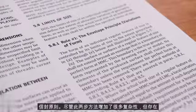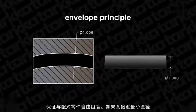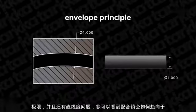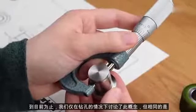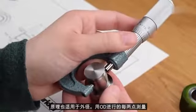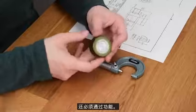While this 2-step approach adds a lot of complexity, there's a good reason for it. Without the envelope principle, bores that measure in spec aren't guaranteed to freely assemble with the mating part. If a bore is near its minimum diameter limit and also has a straightness issue, you can see how the mating pin will tend to bind up in what should be a running fit. Up to this point, we've discussed this concept purely in the context of bores, but the same principle applies to outside diameters too. Every 2-point measurement taken with OD micrometers must be within tolerance, and a ring gauge at the maximum diameter limit must also pass over the feature.